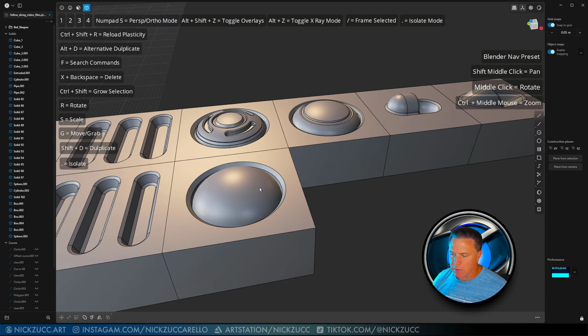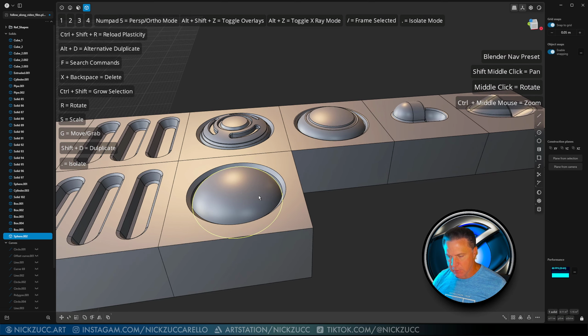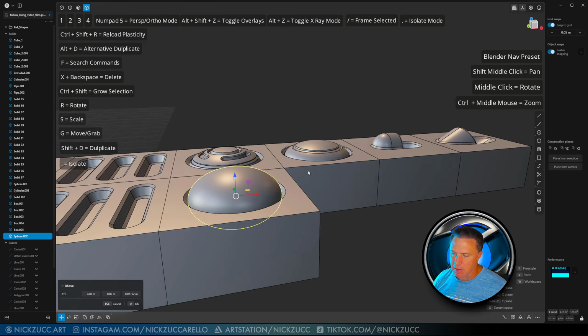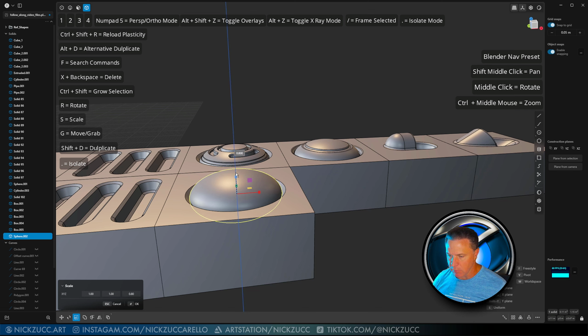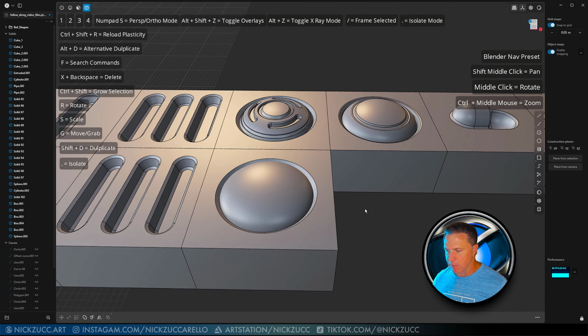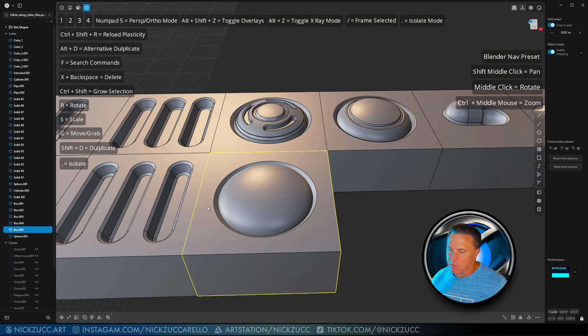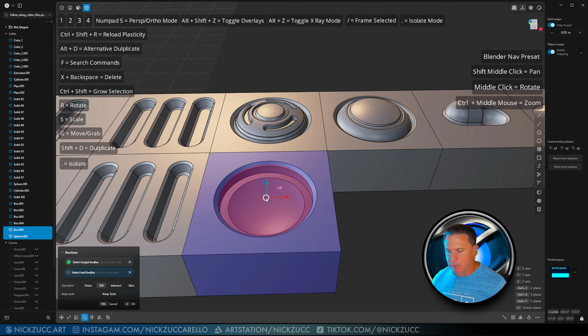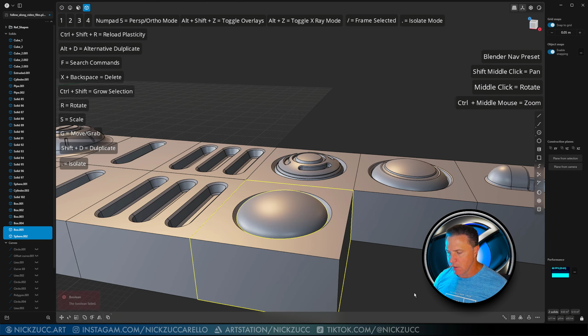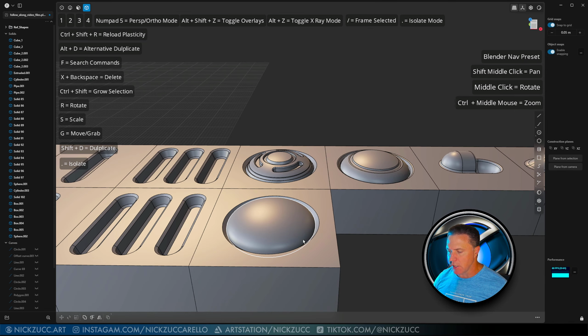If we wanted, we could take this, tap 4, tap G, and that should be in the middle. If you want to hold down Control and then get it right there on that edge, you could do that. That's up to you. Then maybe you'd want to rescale this thing back down. Okay, so there's all kinds of possibilities for how you're going to get this different shape that you've got going on here. Okay, so we can select this one, we can tap Q, Q, and then we can merge those together, hit OK. So those are actually now one shape.